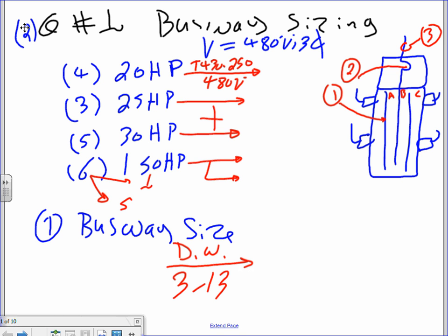The first thing you need to do when we size that baby is go to 430.250 under 480 and find the full load current, right? We're going to size it based on the full load current. So the full load current, guys, will be 271 times 4? I can't read my handwriting even. Can anybody verify that one?